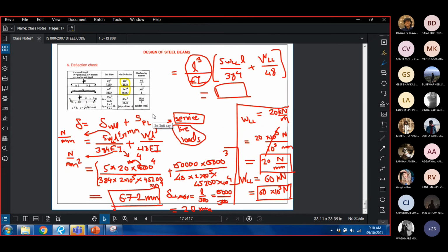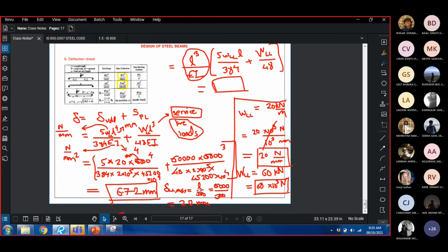Third check, simple, deflection का check. तो deflection में हमको live load deflection देखना है. So while substituting these values, make sure that you use service live loads. डाल दिया. Just plug in the values, make sure that units का consistency होना चाहिए, and then the value, just compare it with L by 300. That's it. Do it a couple of times and then you'll be really comfortable with the procedure. There's nothing complicated conceptually in that.